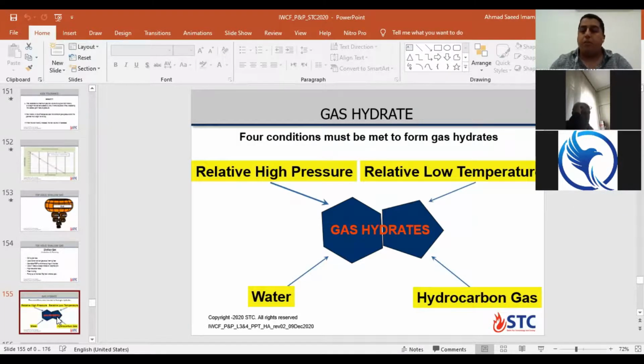In subsea operation, it will really be more difficult. We cannot pump glycol or methanol as with a surface BOP stack. Also there is a long path through the choke line and kill line, so we can find gas hydrate.